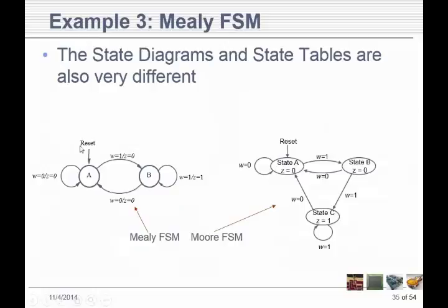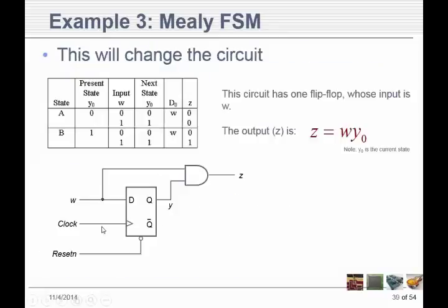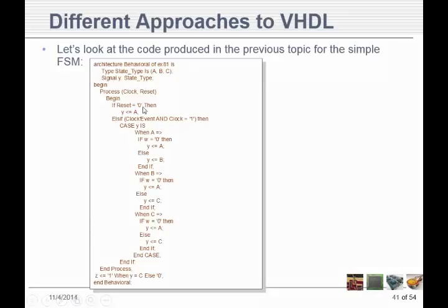Let's go all the way back to here because I arbitrarily chose reset here. I could have chosen it to be somewhere else, but I chose it to be there. So if reset equals 0, then the state is going to be assigned state A. That's what that says. There's only a single quote here because I only have a single variable value, 0 or 1, right? If it was more than 1, then I would have double quotes.